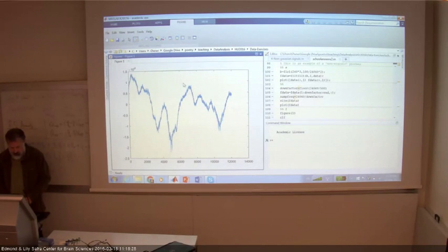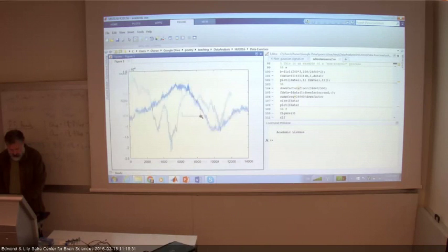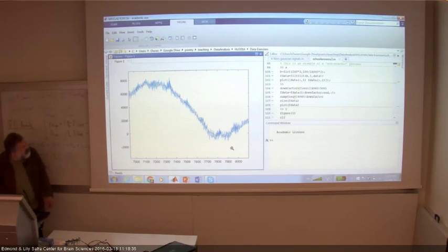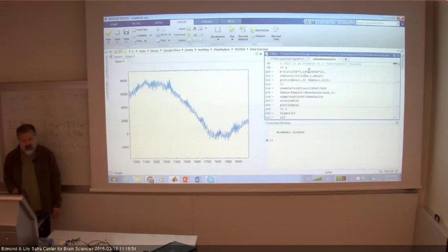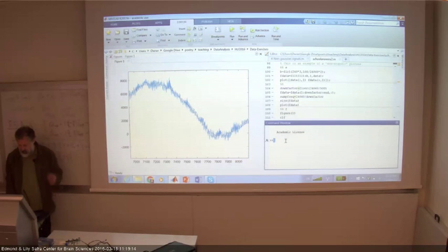So I plotted here the original signal and the filtered signal on top of each other. You see them. So the filtering works. Now the question is how far can I downsample the signal? What we did by filtering is remove frequencies that are much above 100 Hertz. I am allowed to downsample up to twice the highest frequency that remains in the data. So I have to find out what is the highest frequency that remains in the data. This comes from the filter. The filter tells me what's the highest frequency that's relevant in the data.